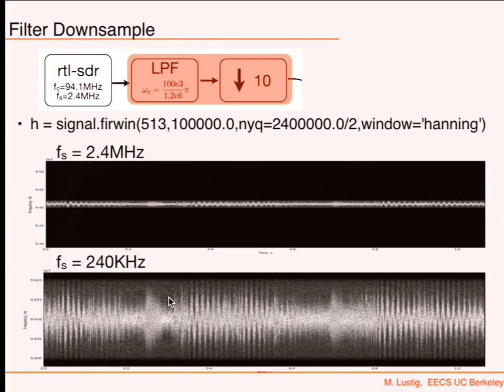Now this goes from minus pi to pi. The whole station, from minus 128 kilohertz to plus 128 kilohertz, will then be minus pi to pi. If I take the DTFT, I get that. It's exactly like we saw last time. If I didn't take the low pass, I would get aliasing. And because I low passed actually to 200 kilohertz, not 240, on the band edges, I see zeros. It looks black, because I filtered narrower than I would actually sample it.